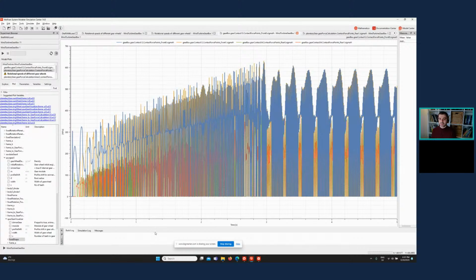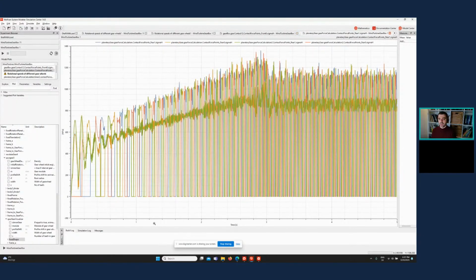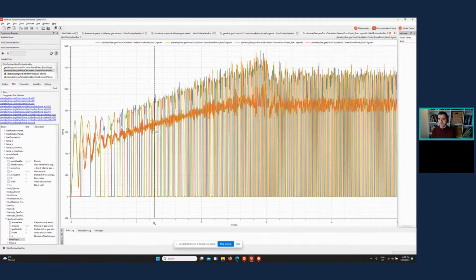All is possible, but looking at the stresses at this level is more beneficial compared to looking at the forces, because just by judging the stresses you can say that this gear material, this design, at least, is within the allowable limit and won't cause any damage even if I run these dynamic simulations.